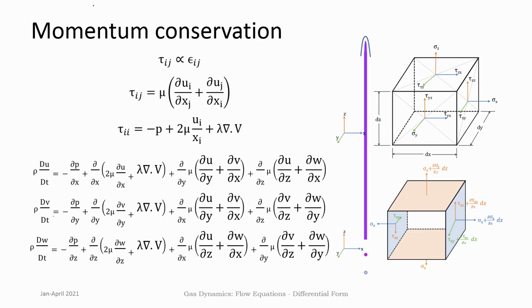Now, what is the particular stress, how is it related to the velocity gradients is what we have to see, and we are considering a Newtonian fluid, and in that fluid the stress is directly proportional to the strain rate, shear strain rate or strain rate, and the strain rates are given by the velocity derivatives. So, this is the Newtonian flow or a Newtonian fluid.